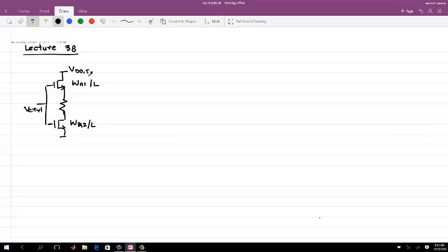You have a ground, so let's say VDDTX is equal to 0.5 volt. In that case, if everything has a 50 ohm impedance top and bottom, this is 0.375 and this is 0.125. Now I need to ensure that, for the up NMOS, let's call this M1 and this is M0.